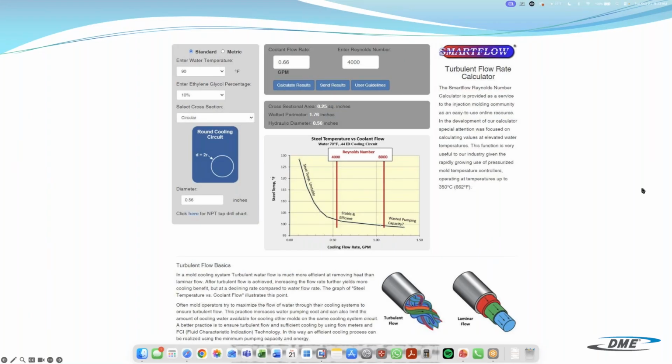So 6 months later, let's just say the tool doesn't seem to be operating as well as it was. Let's take it off and look at it. We will do the same process. We will go to the same flow rate, so the 2.5 GPM, and then we'll check the pressure. If pressure is the same, that means that all things have stayed the same. We likely don't have any scale. But if pressure is increasing, that means that we've got a restriction of some sort through that circuit, because we're having to push with more pressure to get that same flow rate. So likely we have a blockage, we've got scale, or something going on. And that's how we would suggest benchmarking the tool and then doing the checks every 6 months, every year.